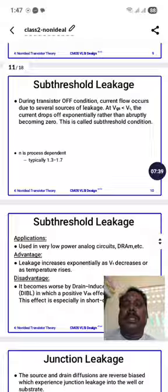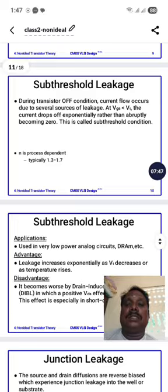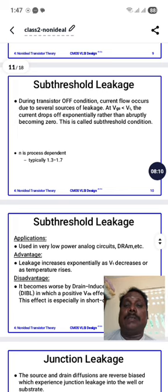the destination. So subthreshold leakage means that even when a transistor is in the off condition, current flow occurs due to several sources of leakage. Usually when the transistor is on, the charge carriers move from one end to another, but subthreshold leakage occurs when the transistor is off also. Due to the several sources of leakage, at VGS less than VT, the current drops off exponentially rather than abruptly becoming zero. This is called the subthreshold condition.